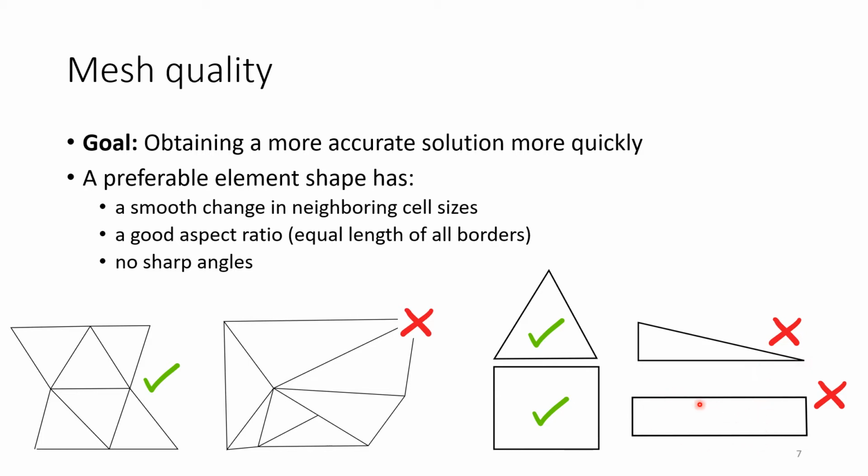But right, also this one, it's a very, very long one. This is not so good, right? And that's something that also applies to the structured meshes, right? You don't want to have your spatial resolution X and Y diverge so much, right? You want to have it in a good aspect ratio.